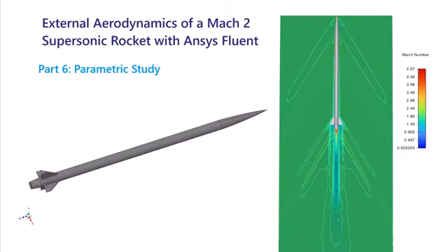It is important to note that only simulation case inputs can be parameterized within Fluent itself. To iterate through small changes in geometry, such as fin position or fuselage curvature, workbench integration and advanced CAD knowledge is required, which is beyond the scope of this video series.